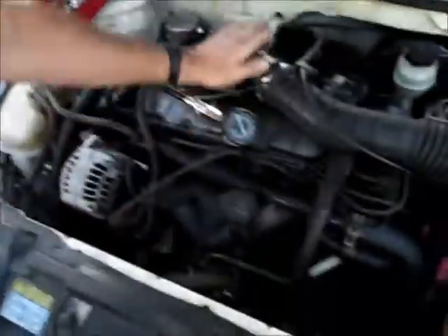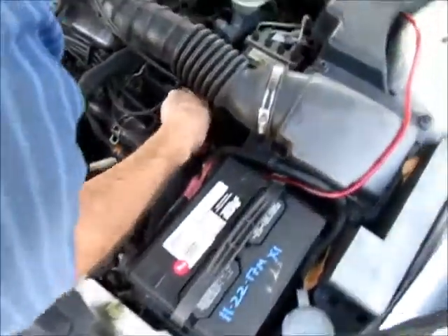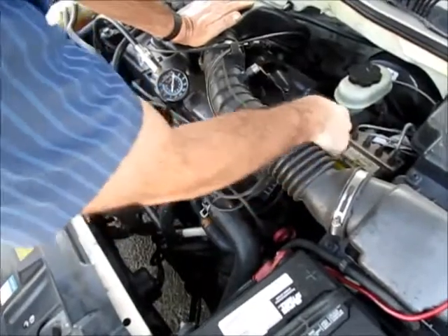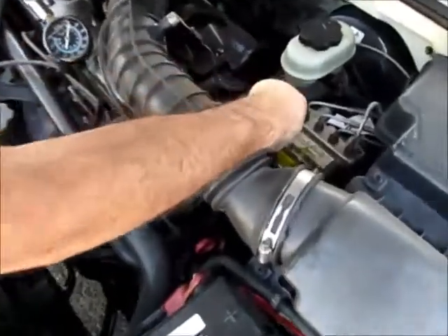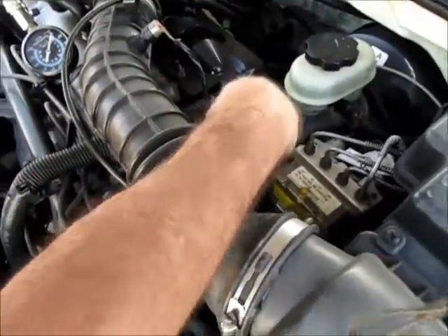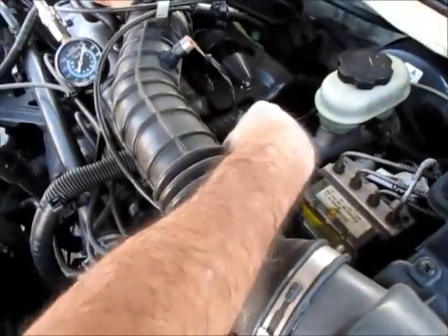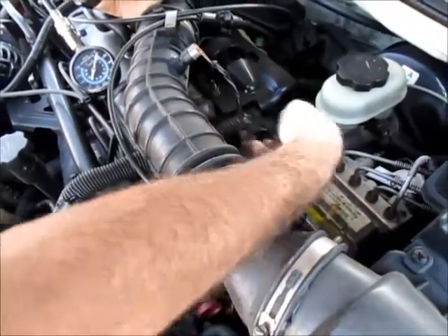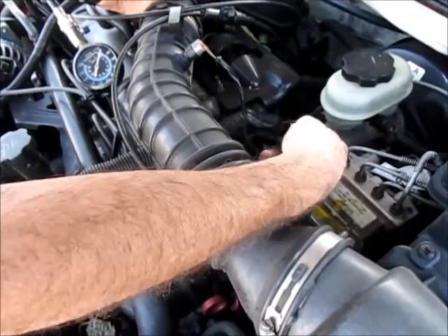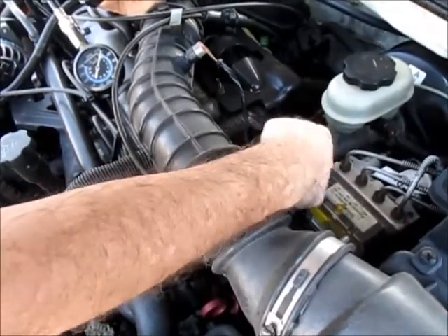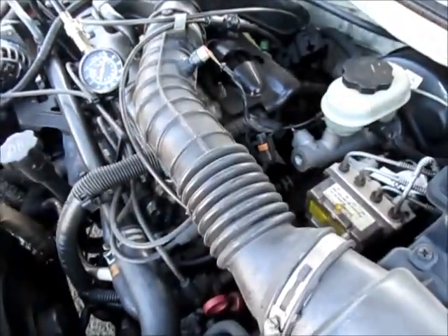So the way you do that is come over here, and the distributor has a power plug. Can you see this power plug? See what I'm doing here, Tom? This power plug you can just unplug. I've already done it before, but just unplug that, and this will take all power off of your ignition system, and it won't crank. Okay, now that we've done that, we can check our compression.